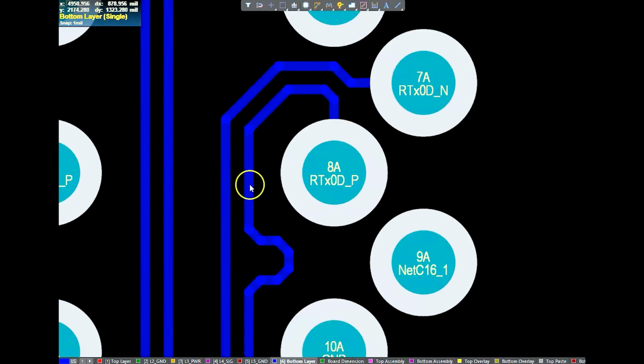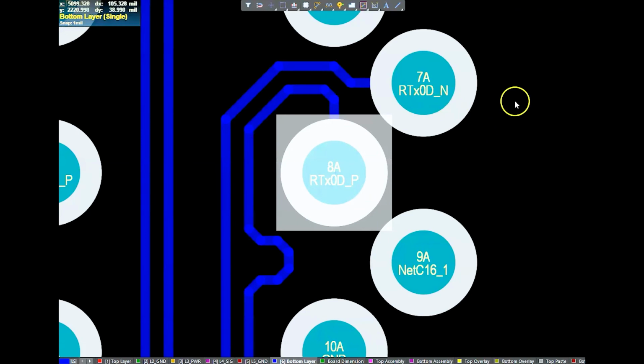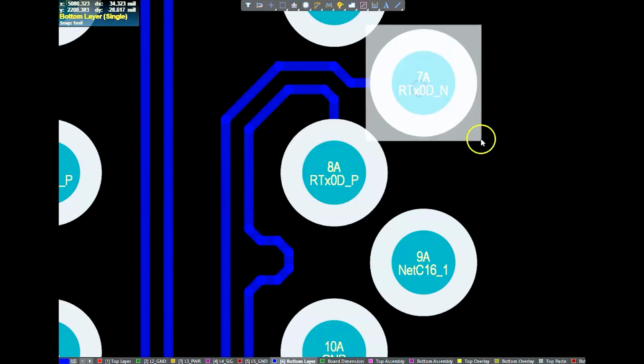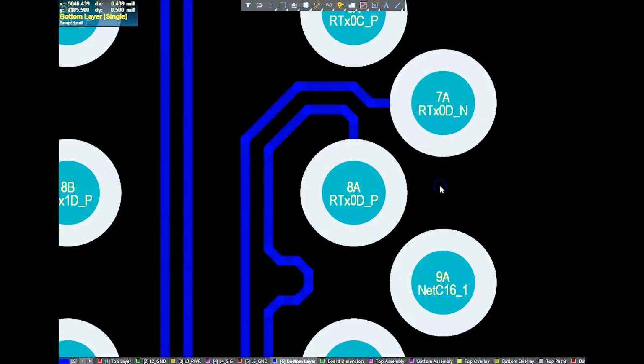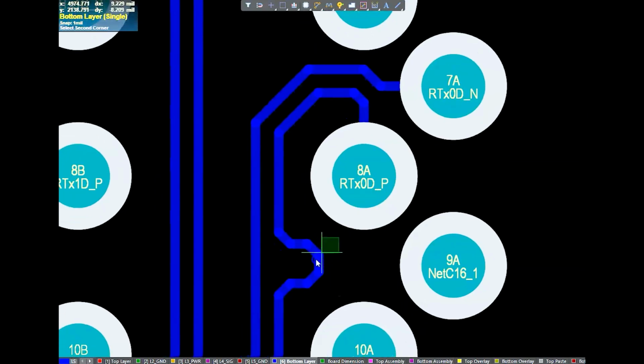So the total length of this side, the positive side, is equal to, or very closely equal to, the length of the negative side of the differential pair. And so by doing that, you can ensure that the signals are read out properly. So we're going to do another video that explains why you actually need to maintain this and some of the different ways or different styles that you can use to enforce this type of section here.